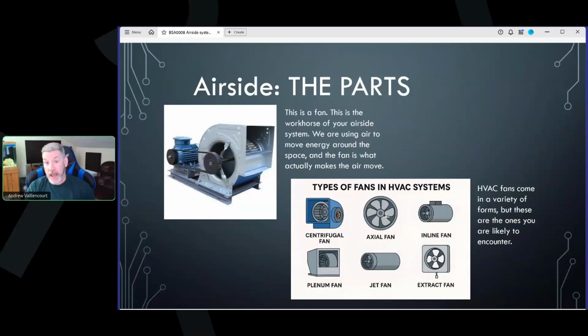It is a style of axial fan for those purposes, because these are extremely low static pressure environments and you don't need anything fancy to move the air. If there's no pressure to really overcome, and that's all an extract fan is doing, just moving things out, then it's easy to just use this fan. It takes up very little space and uses very little energy. It can move a lot of air under very low pressure. As pressure rises, its ability to move air falls off a cliff compared to a centrifugal fan.